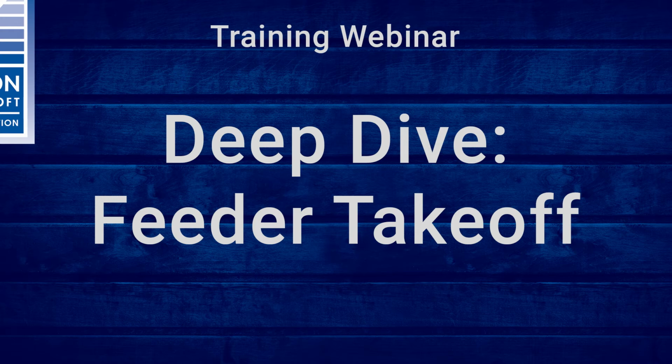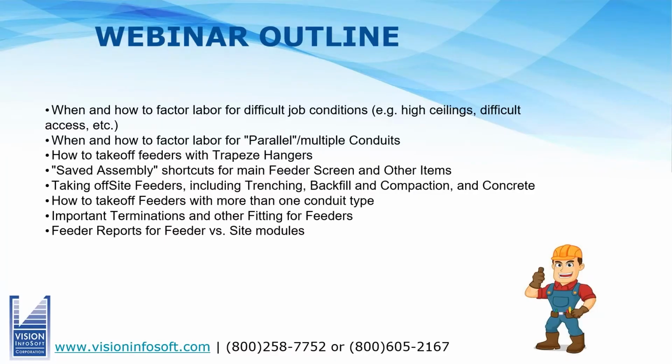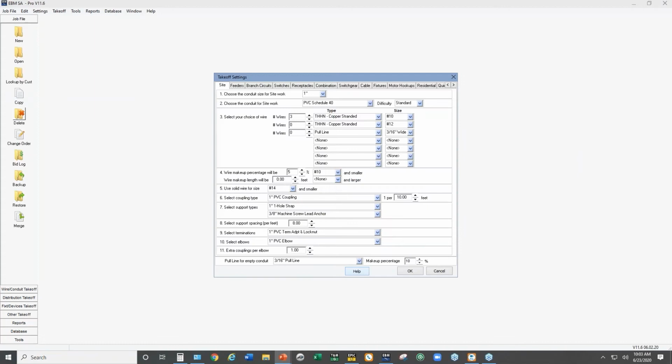So let me flip over to the EVM screen. In the default part of the takeoff program, you may not even know about this part of the program if you haven't visited here before. Under settings, there's default settings for takeoff, commercial. Each takeoff module has its own setup, so that when you open the feeder module versus the branch circuits versus the site, each of these screens has its own default setup. So where I'm pointing here under feeders is the settings you can customize and preset for feeders.